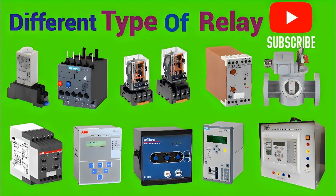and longevity. Actuating mechanism. The actuating mechanism is responsible for moving the movable contacts in response to an external stimulus, such as the application of voltage to the relay coil or the activation of a mechanical switch. In electromechanical relays, the actuating mechanism is usually a magnetic field generated by the relay's electromagnetic coil, which attracts or repels the armature to move the contacts.